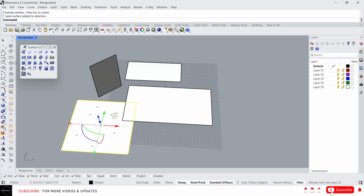Actually, most of the time we won't use these surface creation tools. The most frequently used surface creation commands are planar surface and also loft. Sometimes we'll use patch and network surface.